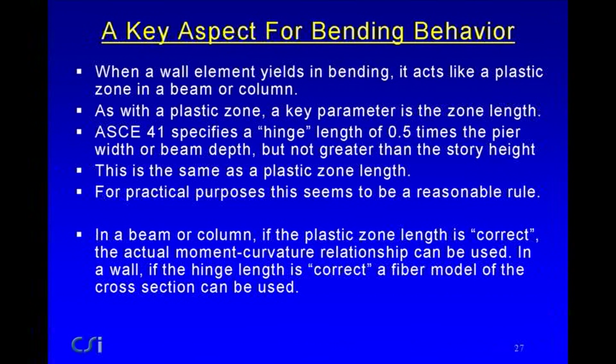Okay, key aspect for bending behavior is that when a wall element yields in bending, it behaves like a plastic zone in a beam or column. It's a constant curvature element. So a wall element which is yielding is very much like a plastic zone in a beam. And as with the plastic zone, a key parameter is what is the zone length.